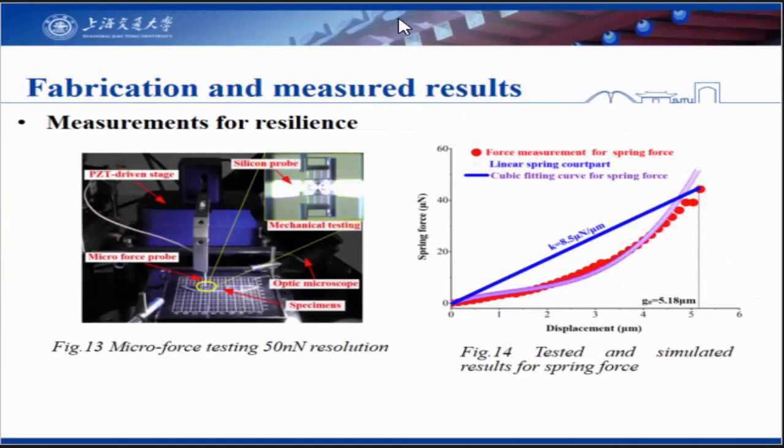Next, let me introduce the testing system. This is a microforce testing system used to measure spring force. Its core component is a microforce sensor with 50 nanonewton resolution. The right figure is the tested and simulated result. Obviously, the clamped guided beam exhibits significant nonlinear behavior.